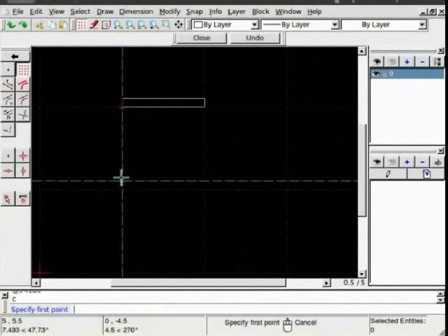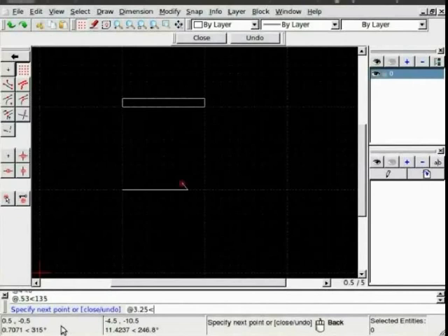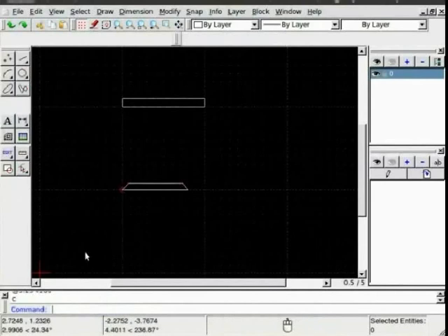I'll first draw it below this and then move it back. So draw a point slightly below the original one. So 5, 5. Next point will be, now this side is a little shorter than 5, so I'm taking 4, angle 0. Then the trapezoidal, or the angular part, which is at 0.53, then angle at 3.25. The top side will be a little shorter at 180, and then C to close it again. So 2 parts are drawn.